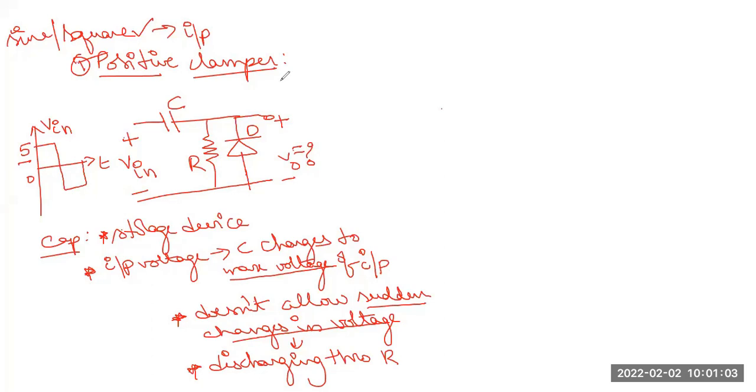So how is that? And in all these things, we are also assuming that our diode is an ideal diode. I am not taking the diode to be a practical diode. I clearly explained why we generally go with the ideal diode. Since there is no V gamma concept, it is very easy for us to understand the operation. So we are assuming that the diode is an ideal diode. Now how to analyze this particular circuit for this applied input? The analysis procedure is the same. Since your input has 2 half cycles, we will start our analysis with the first one, that is the positive half cycle as input.